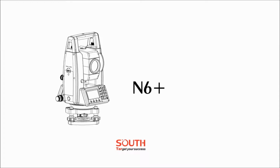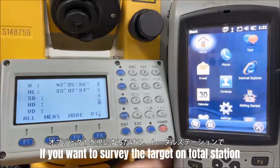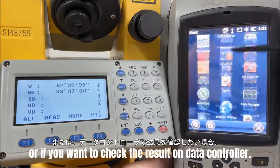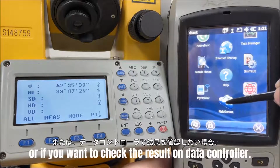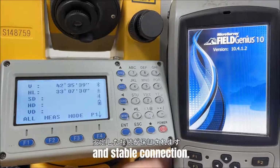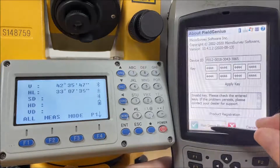Today we will introduce how to connect N6 Plus with your data controller. If you want to survey the target on the total station only by sighting the object, or if you want to check the result on the data controller, don't worry. The built-in Bluetooth on N6 Plus ensures a long-distance, stable connection. Let's use FieldGenius by MicroSurvey as an example.